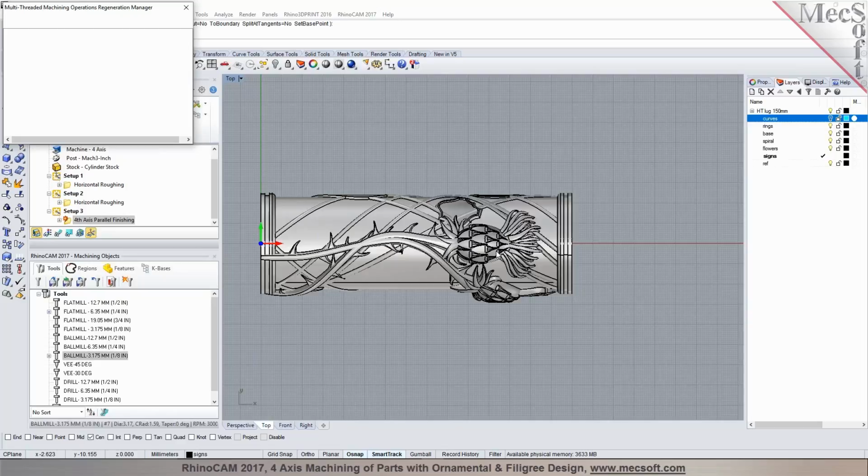So what I'm programming is a long axis cut in here using a 4-axis parallel finishing. So the tool will traverse along the length of the workpiece, and then it'll rotate in step increments based on the step over that you put in. So by the time it makes one full rotation, you would have pre-finished or finished the part. So it's processing the 4-axis parallel finishing toolpath. Now this could work as your pre-finishing, or it could be a finishing pass. And it'll automatically identify all of these features. So you can see that the part in here has several complex features on the model.